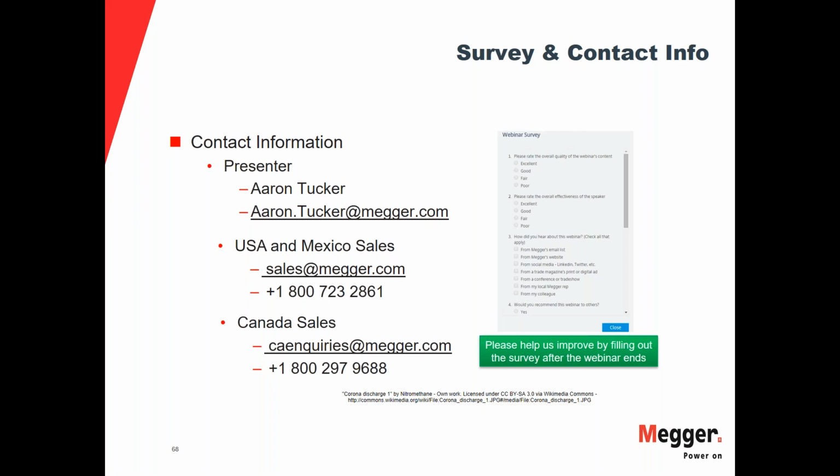Obviously, for the most accurate results, and typically this is a recommendation across the board, you want to disconnect anything coming in on your load side and anything coming in as your main on your primary side. Most people when they do TTR don't just do TTR. They're going to do a bunch of different tests, whether it's power factor or insulation resistance, and all these tests require that you isolate your load from your primary incoming voltage. You also don't want to do the test on a transformer with the wires still connected, because you can induce voltage into things that you don't want to. It's also a safety risk to people down the line.